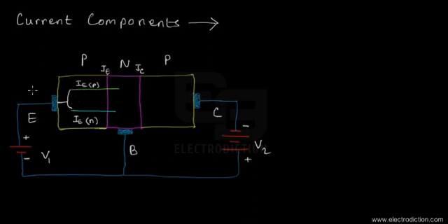So it's quite natural that an emitter current, due to this sort of bias voltage, would flow in this particular direction, from the emitter into the base section, and that's why the current's direction is directed inwards into the emitter of the PNP type of BJT over here.